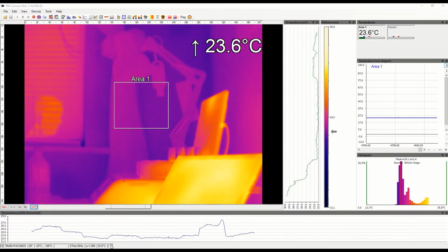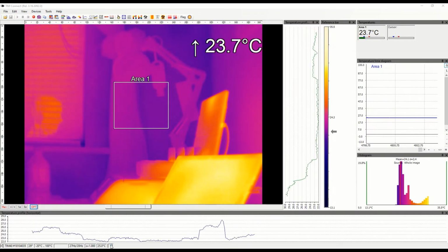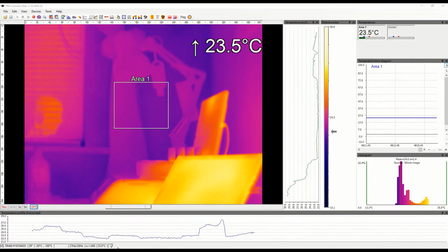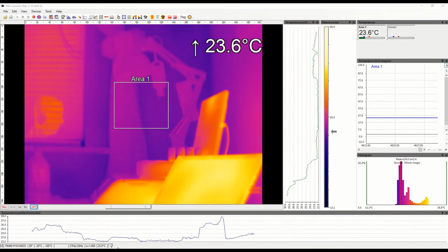The flag is used to control the temperature drift of pixels over time and is a mechanical shutter between the lens and the detector that periodically moves across and covers the detector. It then uses its own reflected image and known temperature to readjust for thermal changes.